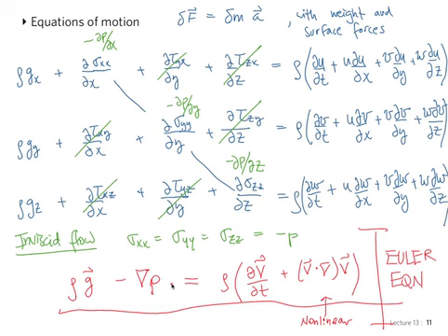Velocity is one of the unknowns, and we have a term here that multiplies velocity with derivatives of velocity. So it's a nonlinear term. Okay, velocity multiplied with its own derivatives. These nonlinear terms make this equation very, very difficult to solve. There's no general solution. The only approach that you have in general is the computational approach. Write a computer program that solves this in space and time in the most grueling way.